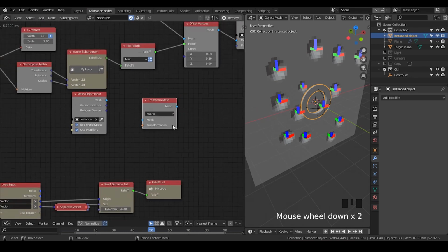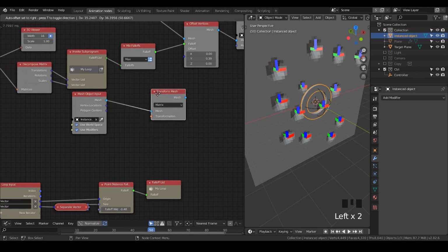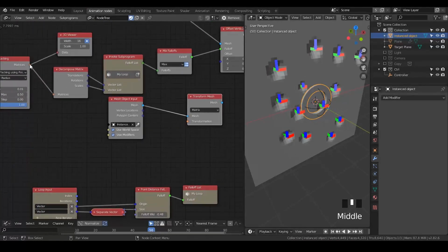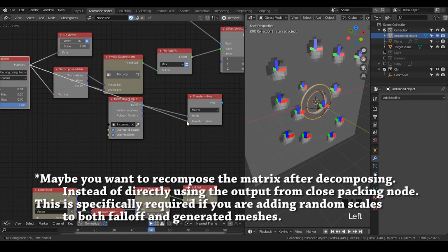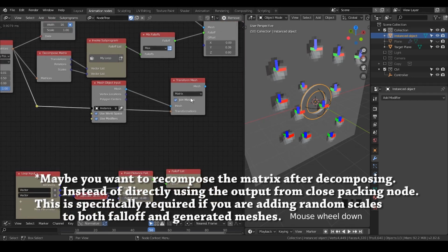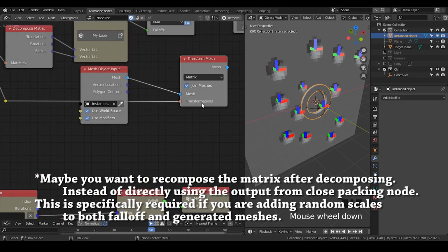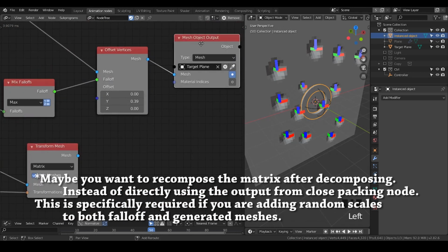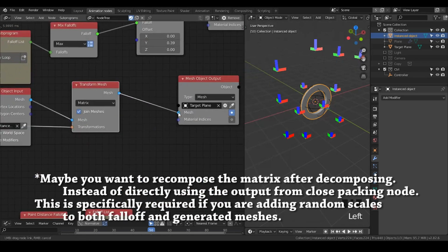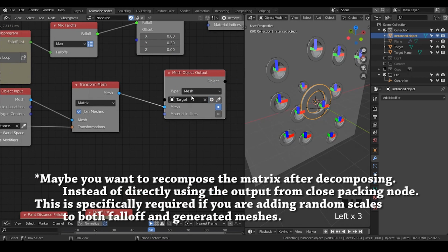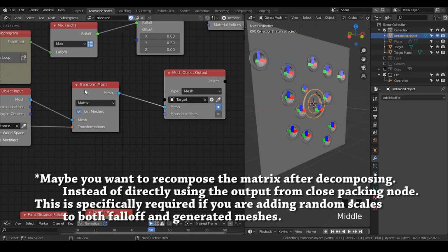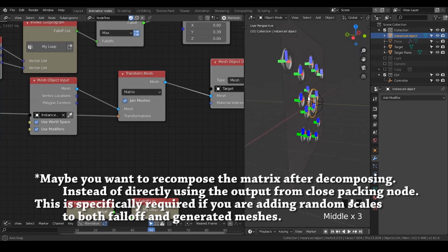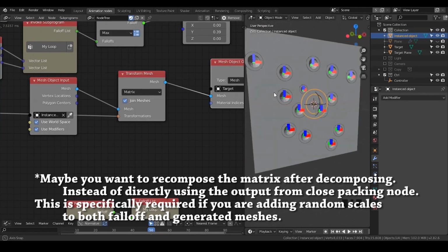This node is very tricky because it does not only transform the mesh, it also replicates the mesh if you want. So now if I put the matrices into place, into the transformation, then you can see it actually allows a multiple input of transformation, and what it finally does in such a case is it will actually replicate the mesh. So this is what actually finally happens. We instance the object, and this is cool.